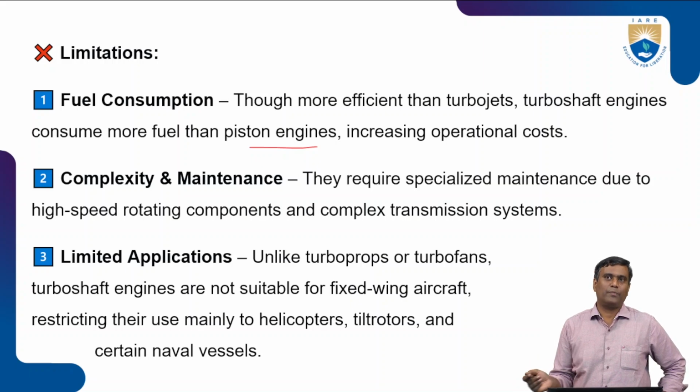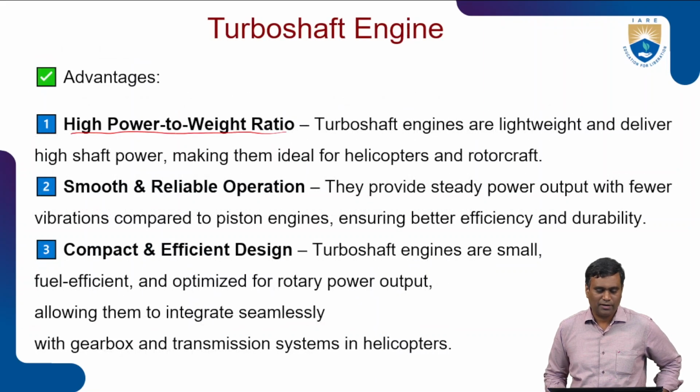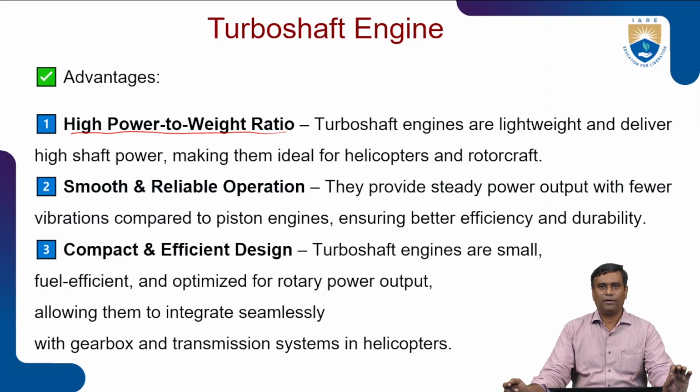These are only optimized or designed for rotor blade operations, that is VTOL applications, that is helicopter applications, helicopter tilt rotor applications also, because a few hybrid configurations are there. Tilt rotor, which is designed for horizontal takeoff, and at the same time vertical takeoff also. Tilt rotor, where the rotor will tilt, right? So these are a few advantages and applications of turboshaft. Turboshafts are only suitable for rotor blade vehicles.